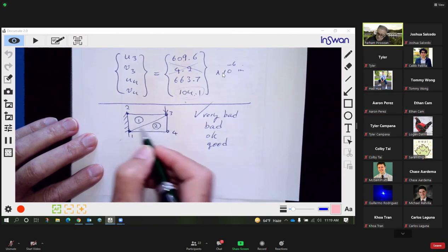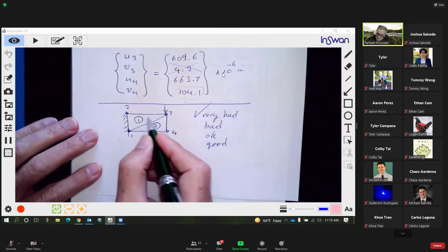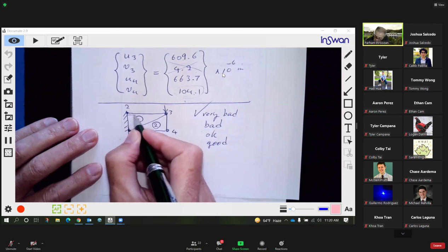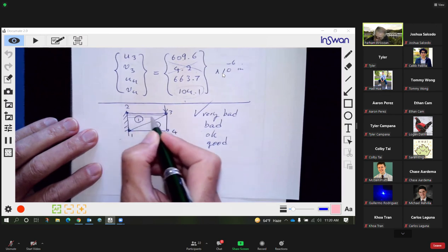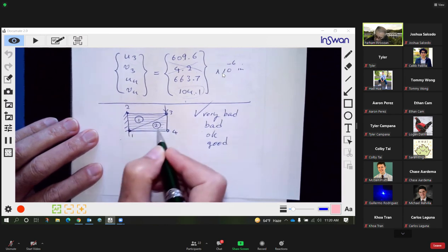Well, because this is giving one stress over this element. For example, element 1, we get 1 sigma x. There is just 1 sigma x for this, but it's not correct. I mean, this stress is varying. Even these fibers are in tension. Then these fibers at the bottom are in compression.